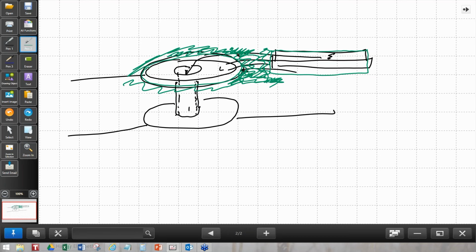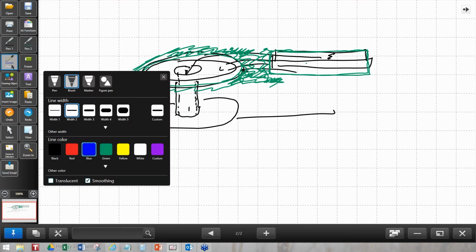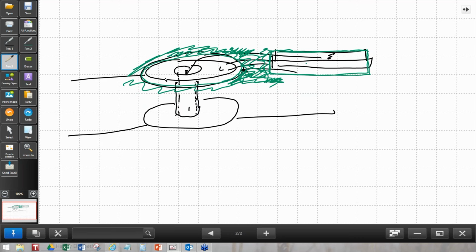Well, it depends. Do you really need to leave all of the pad uncovered? Not necessarily. Sometimes people decide that they want to tent part of it but leave the hole open. Generally, most of the time people say, I want to leave that completely uncovered. My guess is why they do that is because when you have a surface mount pad, you want to leave the entirety of the pad open.